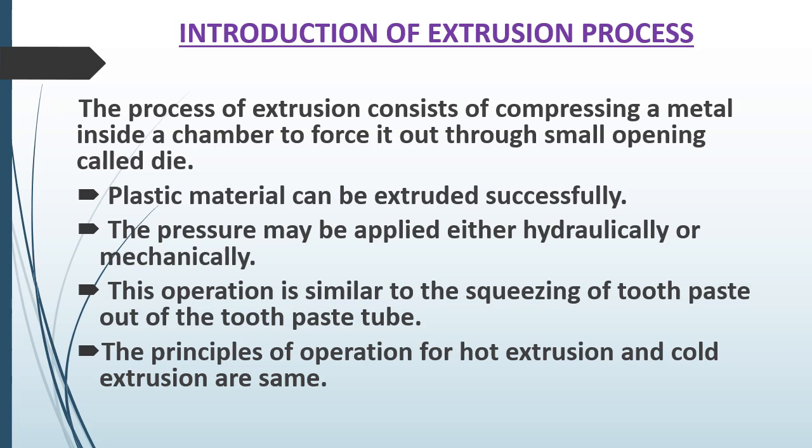Extrusion may be defined as the manufacturing process in which a block of metal enclosed in a container is forced to flow through the opening of a die. The metal is subjected to plastic deformation as it undergoes reduction and elongation during extrusion. The section of the product will depend on the shape of the die opening.